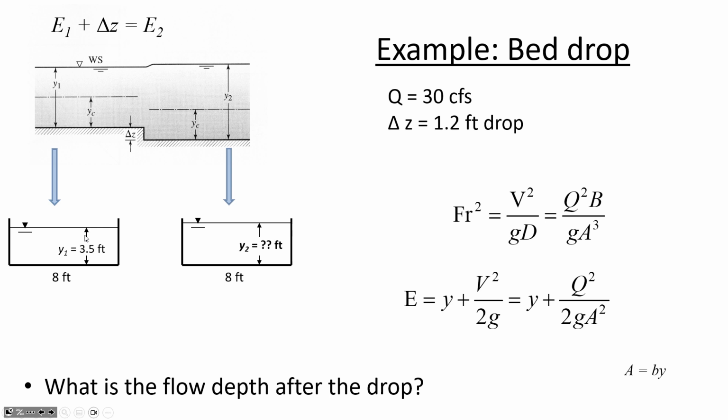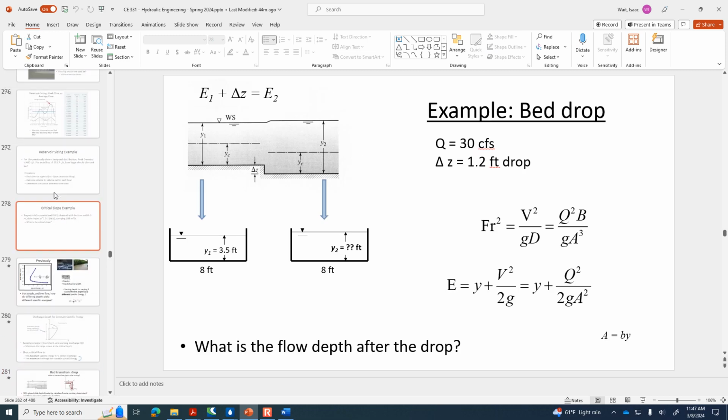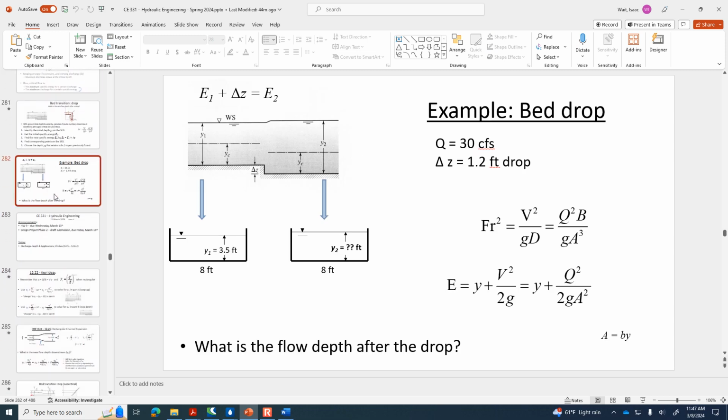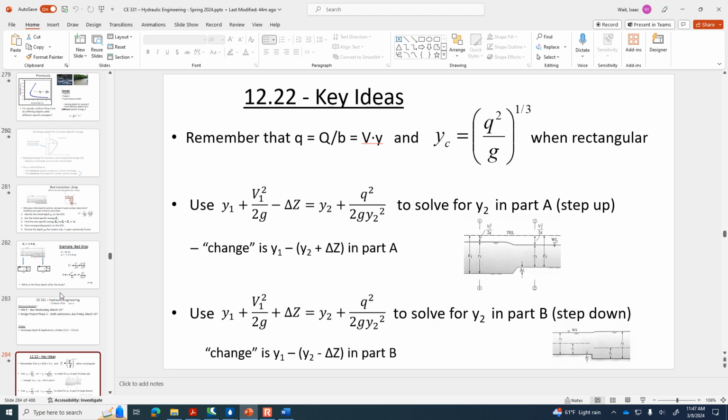Is it supposed to be 1/2 or 1/3 power? It's supposed to be 1/3. Okay. Yep, the formula for Y sub C for the rectangular channel. Whenever you were writing it down, you said 1/2. Did I? Yeah. Yeah, it's supposed to be 1/3.